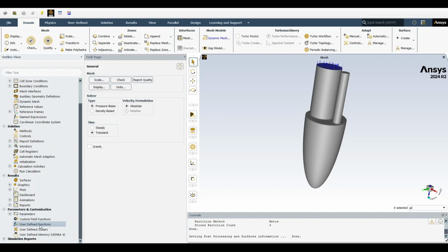and as we already have copied the necessary files, we're going to compile here user-defined functions, compiled, add, and we're going to select the 3 profiles, which is BC profiles and UDF X dynamic mesh and X points. So, okay, here it is important that you check the use built-in compiler if you already haven't built the UDFs. So we're going to build this. It is also important that every time you build the UDF library, you have to delete the previous one after you unload it, of course.